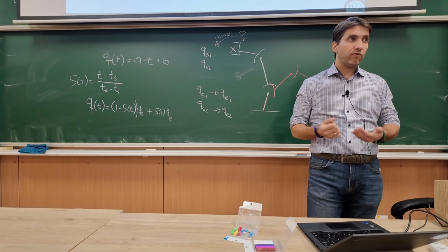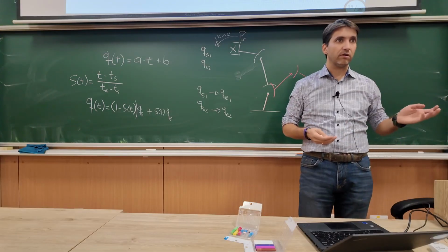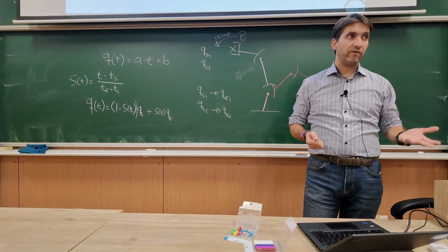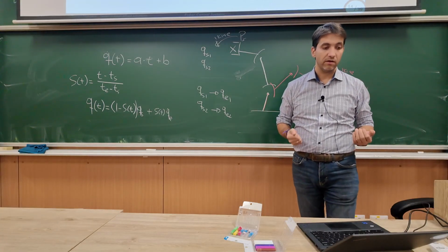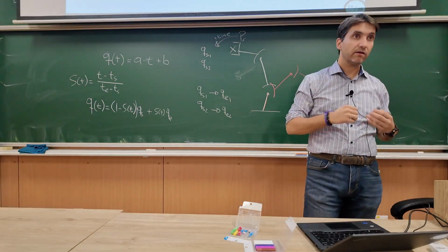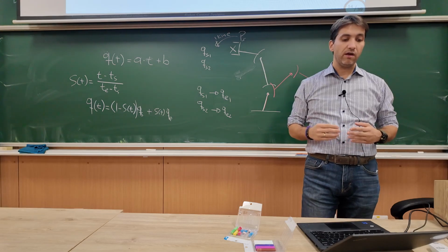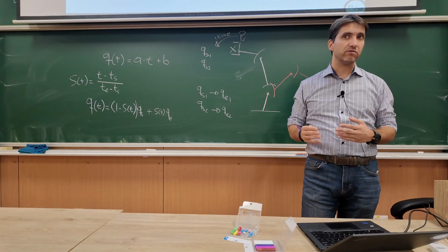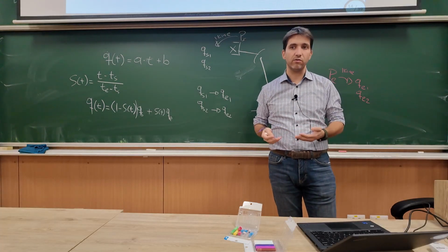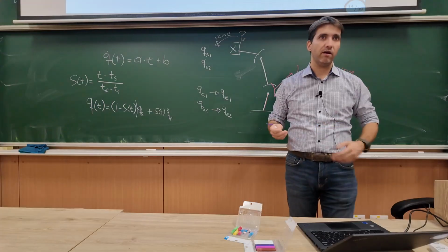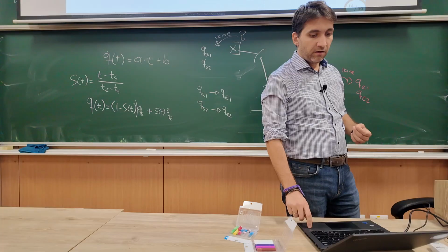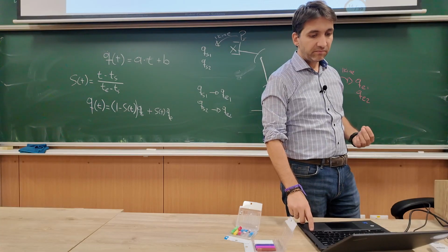And acceleration is related to forces, right, from Newton, F equals ma. So when I have high accelerations, I will have very high forces as well. So what your colleague was saying: in order to start the robot at the beginning, I need very high torques, and in order to stop it again, I will have very high torques, which in theory should be infinite. In a real case, it will be very high, and that will result in vibrations and stops. So how do we solve this?